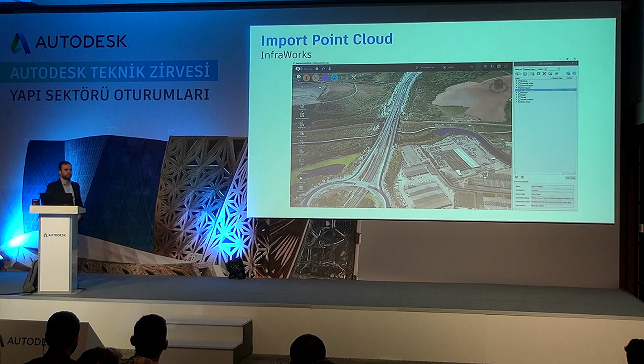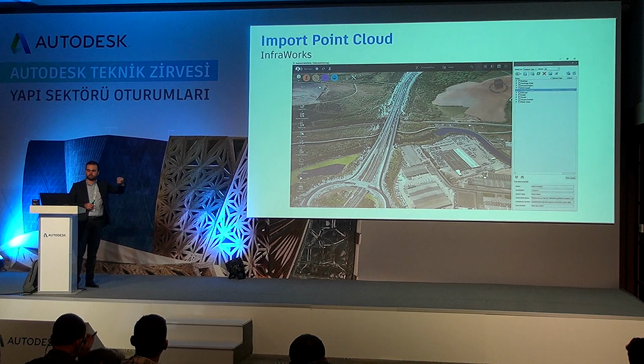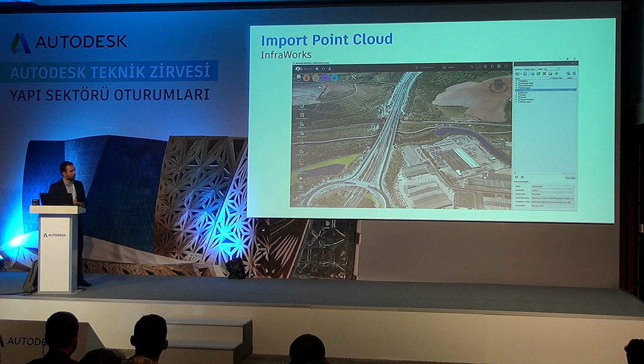If you go online and check more about laser scans, you will find that some of those laser scans or points have colors, especially for buildings. What laser scans do, other than sending a laser beam and capturing the exact location of every point, X, Y, and Z, is they actually take 360-degree pictures, and they analyze the picture, take the color from every pixel and put it on the point cloud.